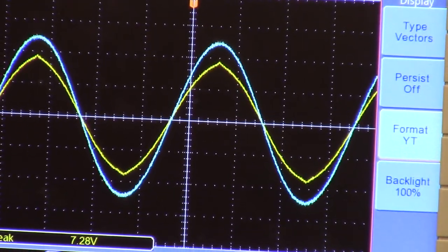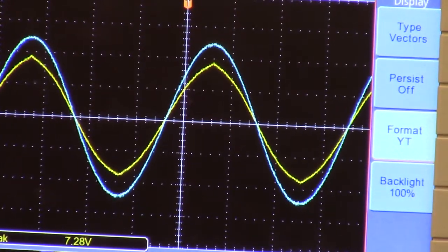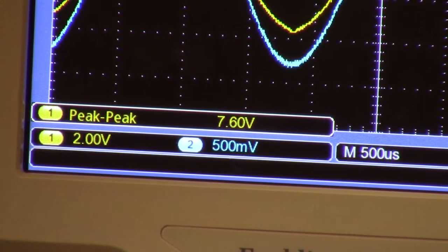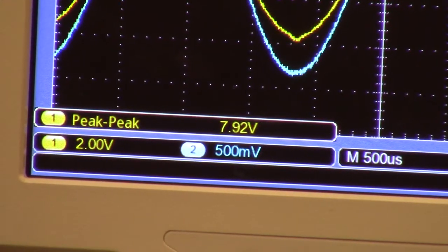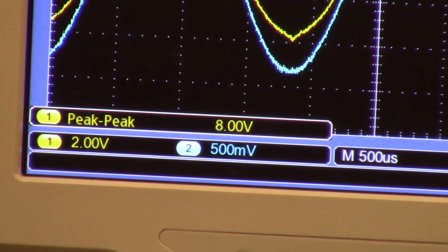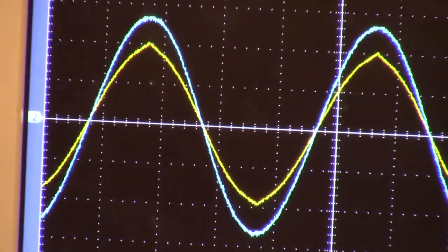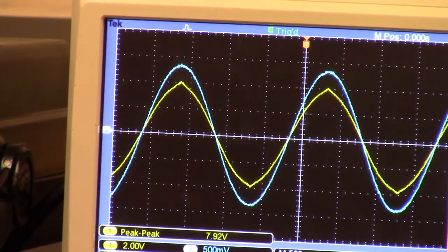Let me then make this measurement, but let me warn you, I want to make sure channel 1 is set for 8 volts, because I don't think it was. So channel 1 says 7.36. So I'm going to up it to 8, or near 8, depending on how finicky it is. I saw an 8, now I see an 8 again, and then it drops down to 7.92, so it looks like the digital converter is not giving me anything in between. So I'm going to call that 8 volts, all right?